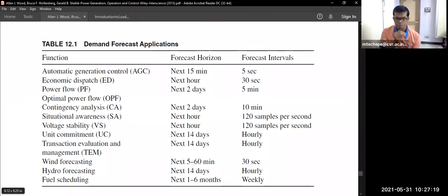And also wind forecasting, like what is the velocity of the wind? Velocity of the wind means like 45 kilometer per hour. Okay, if the wind speed is 45 kilometer per hour maximum, and minimum is 15 kilometer per hour only, they may run that particular wind turbine. If it is less than 15 kilometers per hour, even though they run, the efficiency might be dropping. Okay, so efficiency might be dropping, now definitely they may stop that.